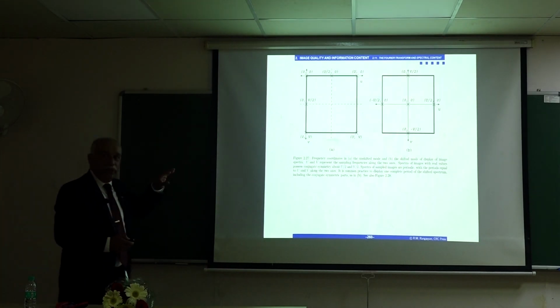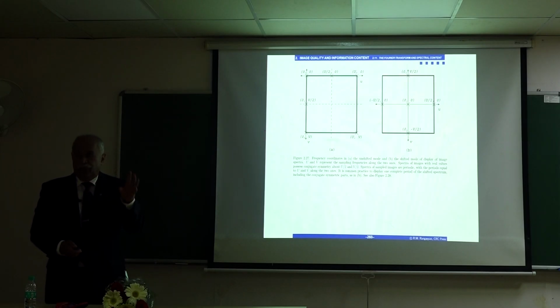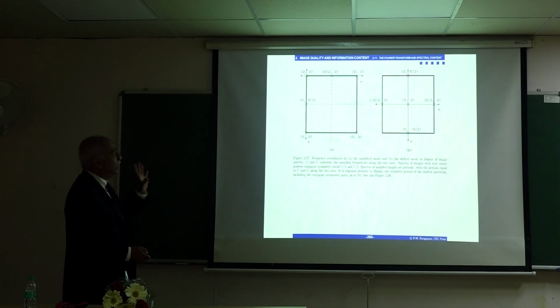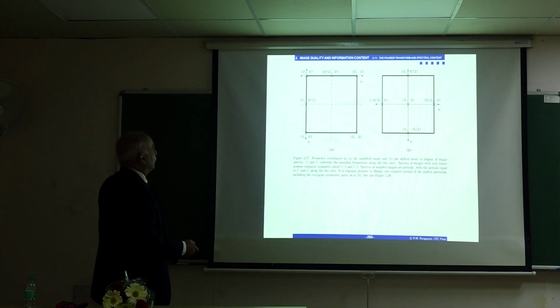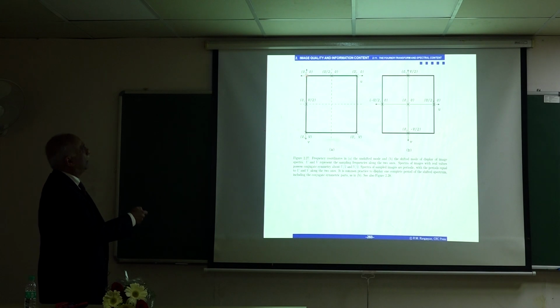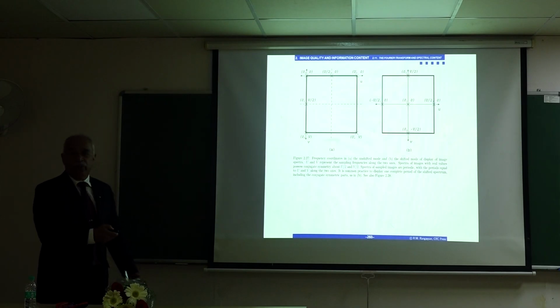The Fourier transform in 2D is typically folded. We sometimes do that in 1D also, or we just display the first half. But in 2D, the full Fourier transform is displayed, typically. So the frequency coordinates, when you compute, you may get it with origin there. But for display, we want origin in the middle. Origin is DC, 0, 0 frequency.